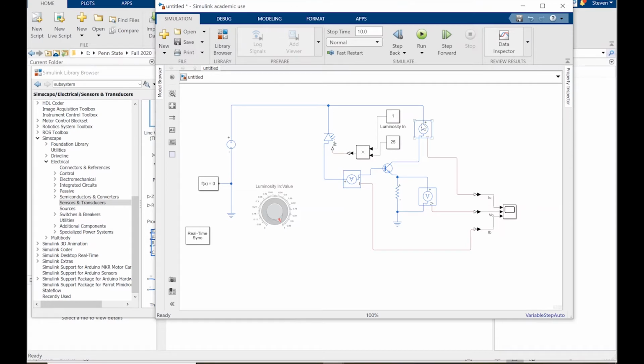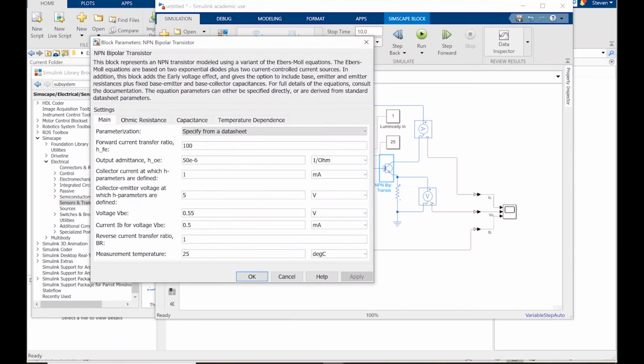Yeah, I'm also talking about how the math is going to work out, that the current through the transistor and the voltage across the resistor are actually going to work out to be exactly the same, because I've got 0.5, yeah, so 0.0005 amps times 1,000 is going to be the same thing.